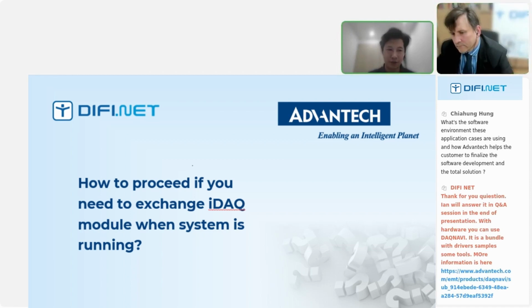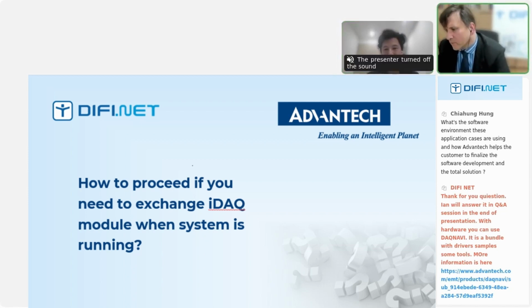And for the application layer, if you're running an application and suddenly you unplug one of the modules, it's really dangerous because maybe you are controlling something. So before you do this, you need to stop the application, unplug and replug it, and then start your software. That's my suggestion. And for sure, it's hot swappable. To simplify the process, if there are some problems on one side, then it's possible to stop and exchange.